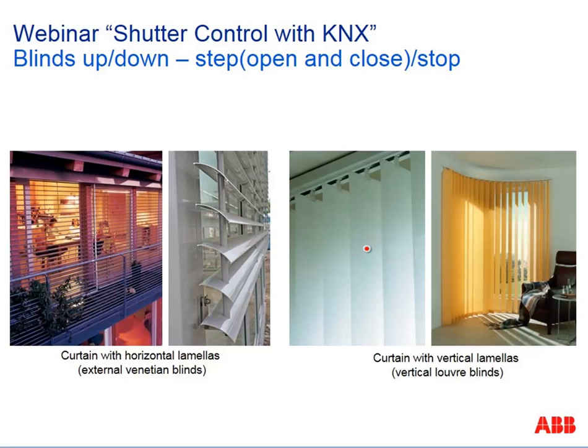You find this also sometimes in projects. And in the Middle East region, for example, we have in private buildings standard curtains also operated via KNX. So all these things are possible. So not only up and down and stop here is a topic, but also positioning of the lamellas. Practically, you do it the following way: you run the motor by, for example, long operation on the push button, and then you can run the motor stepwise by short operation, or vice versa is also possible. So double function on a push button.